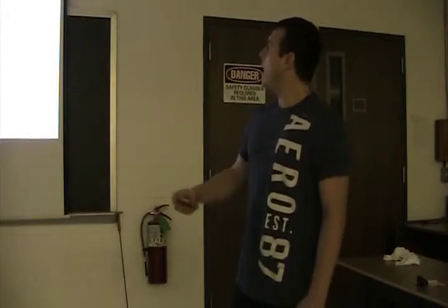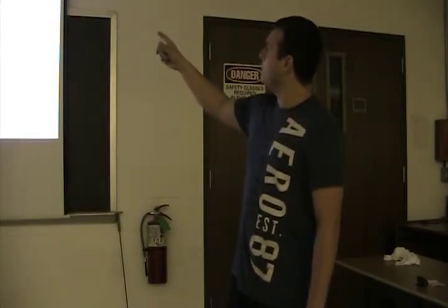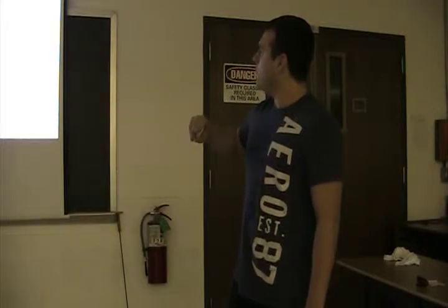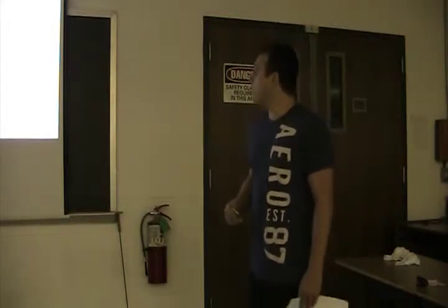Then the next thing, I calculated the speed of sound. I used 1.4, which is for an ideal gas, so that should be kind of skewed. And then I calculated from temperatures 403 Kelvin to 413, which is 130 and 140 degrees Celsius.